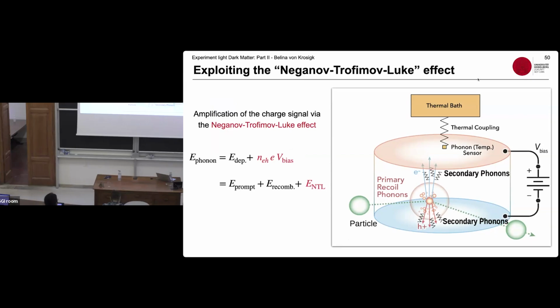Now, we are not in vacuum, clearly. We are in a silicon crystal, a germanium crystal, any kind of semiconductor crystal. And what is happening when you apply a really strong field is that the electron hole pairs start to accelerate, but before they get to their terminal velocity, they are seeing other atoms, other nuclei, ions. So they are not able to just accelerate freely, but are in this entire lattice, and they interact with the surrounding atoms and transfer their energy into lattice vibrations rather than accelerating to their final velocity.